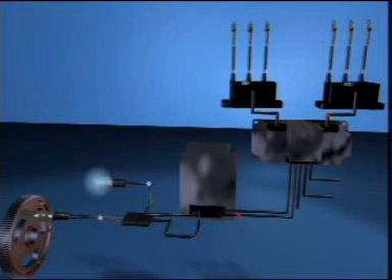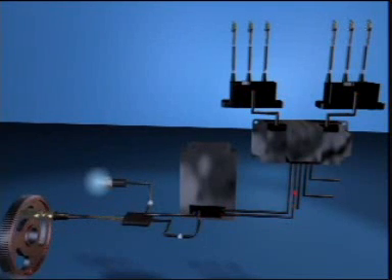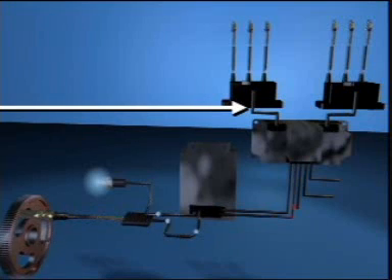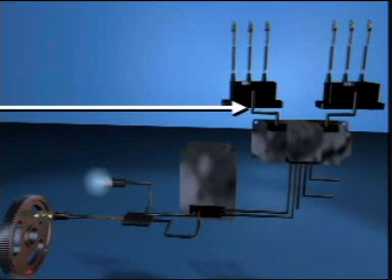The ICM has a built-in engine diagnostic capability. The ICM monitors the primary ignition circuit for continuity on the coils for cylinders 3 and 4. If continuity is not present, the system will not open the fuel valves and the engine will not start. Therefore, disconnecting the harness from either of these two cylinders shuts down the engine.